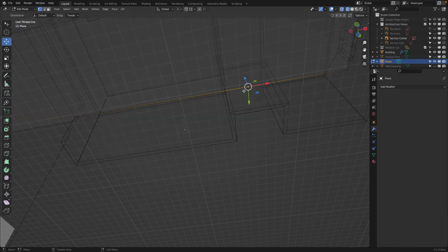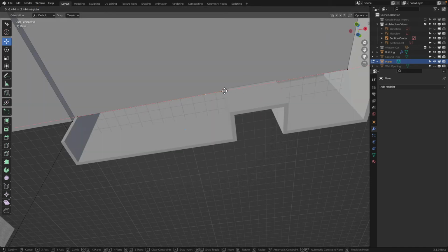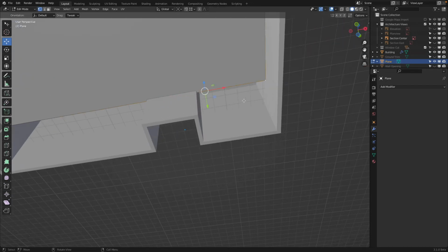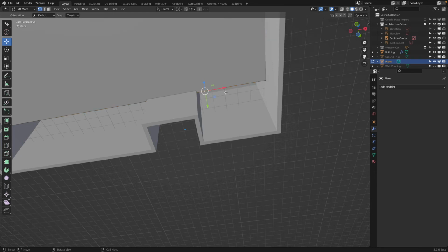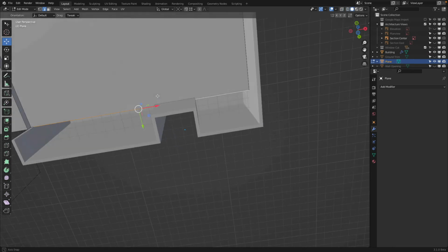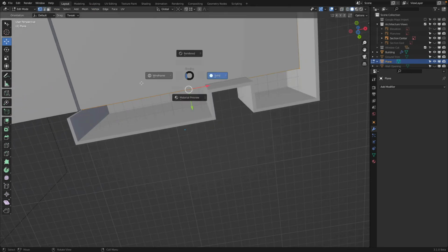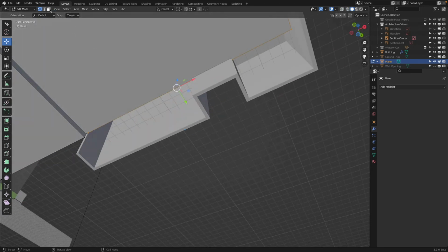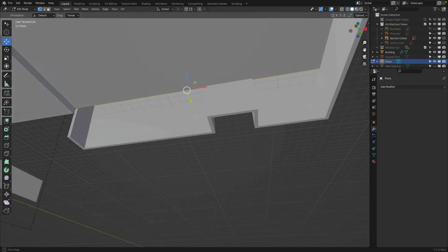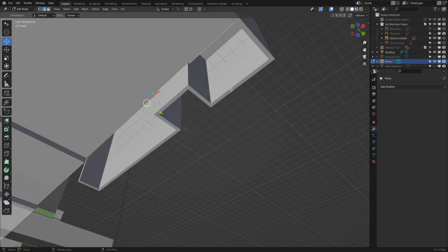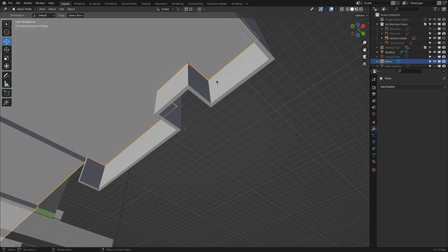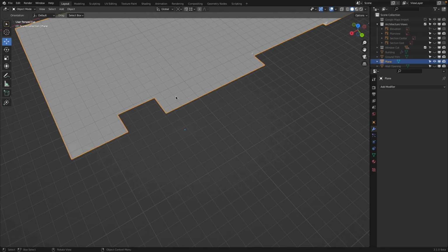Where's the other point? I know it's right there. And snap it to there. Then subdivide and click this point, hold control, bring to there. And then I can, this is important, select this edge and this edge. Not via points, because if you select points, you see this edge in between is selected too. Edge select U and U, and then E and Y, hold control, snap there. Shift H, there you see what we did.